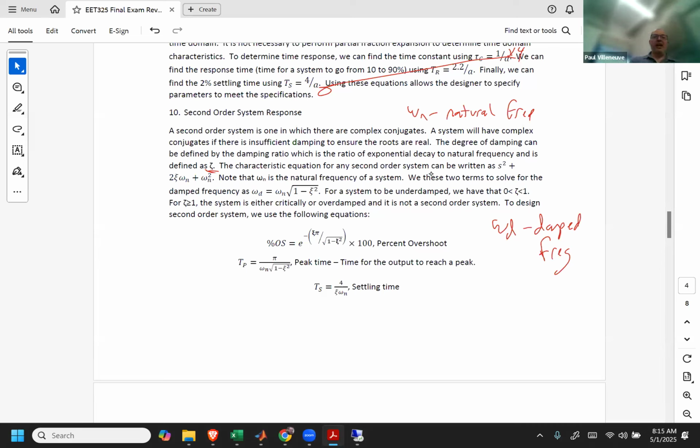And so for a second order system, you always had to have an underdamped system because there is not sufficient resistance, and it doesn't have to be electrical resistance. It could be mechanical resistance or anything like that. But there has to be sufficient resistance to make sure that the system doesn't overshoot. If there is insufficient resistance, then you actually have some overshoot. You have some ringing in the system. And that's because when you take the quadratic equation and you determine your roots, you end up with